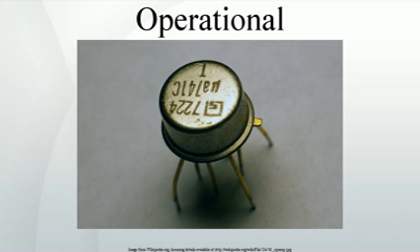On the other hand, a small positive change in voltage at the non-inverting input, Q1 base, drives this transistor into conduction, reflected in an increase in current at the collector of Q3. This current drives Q7 further into conduction, which turns on current mirror Q5/Q6. Thus, the increase in Q3 emitter current is mirrored in an increase in Q6 collector current, resulting also in a decrease in base drive for Q15. Besides avoiding wasting 3 dB of gain here, this technique decreases common mode gain and feed-through of power supply noise.